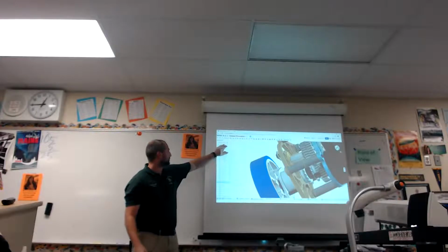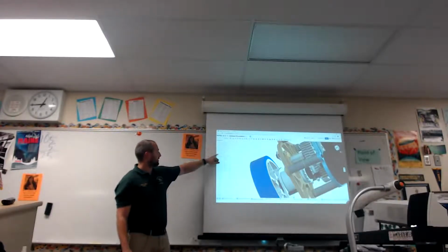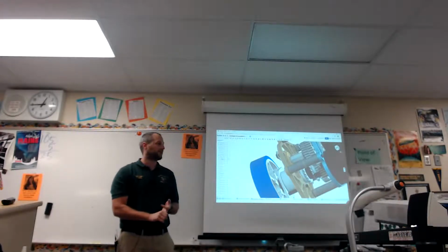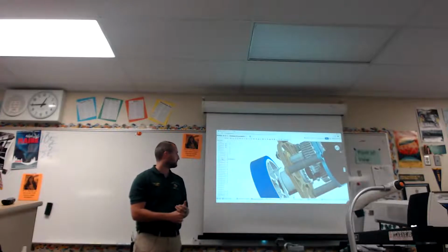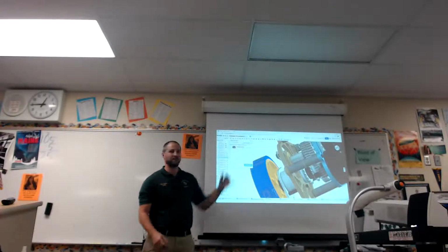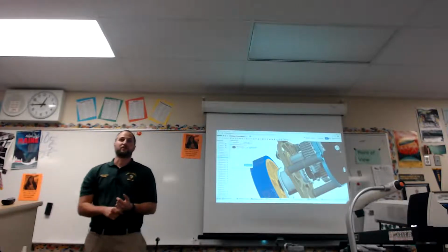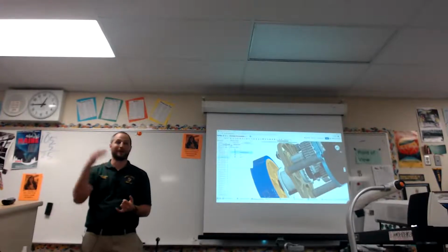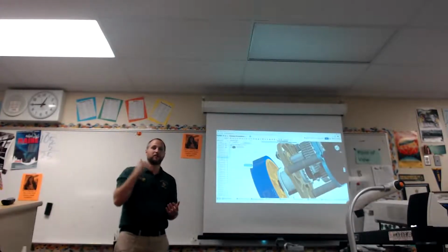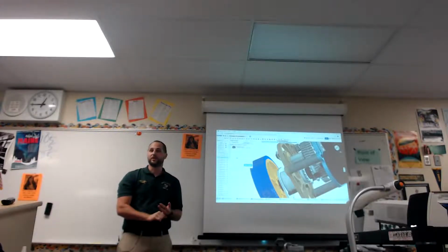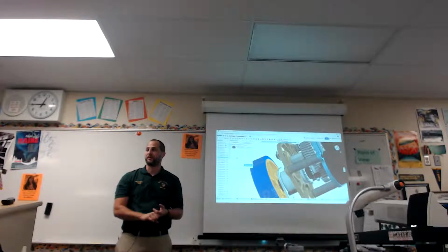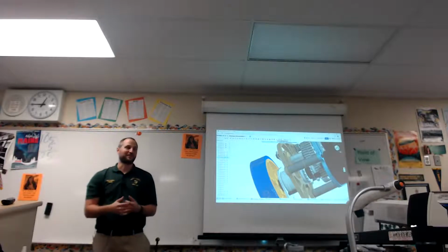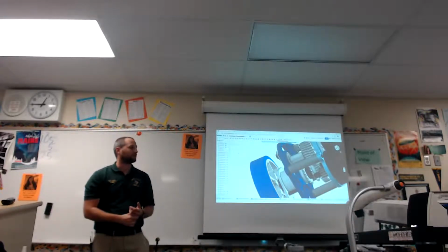Also, if you look, scroll up here, all these different parts that are McMaster parts, our screws, our nuts, et cetera, they're all grabbed out of a linked document. And if Tony clicks on one of those links, it pops up and gives you the option of updating independently. So when you load up your assembly, you're not updating every single part and then trying to troubleshoot why the whole thing exploded and doesn't work anymore. You can grab each piece individually and choose when to update it, which version to release, and which one to keep back. So it lets you see your problems a little bit clearer because they're breaking individually instead of 10 pieces at once. Let's go back to our slides.